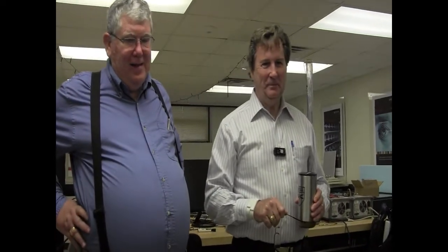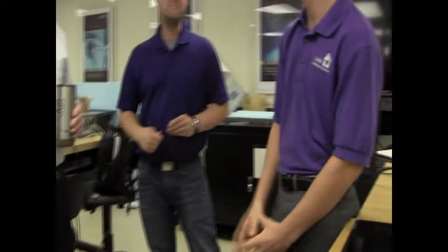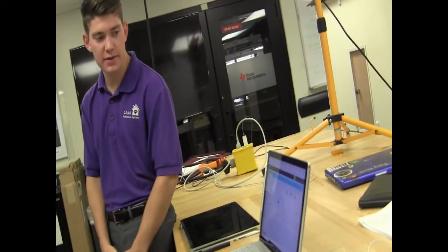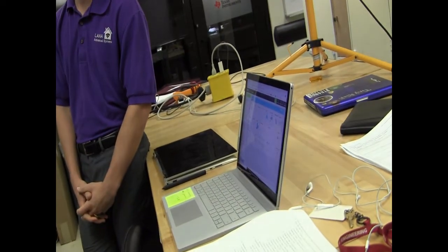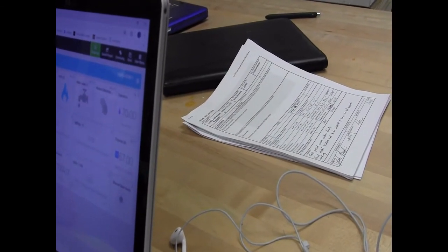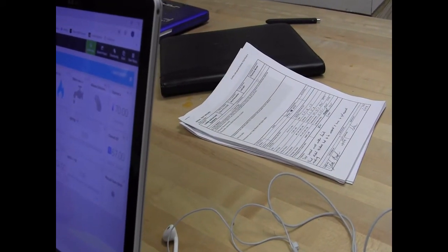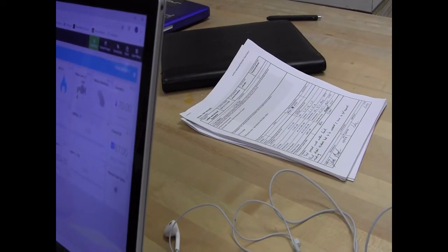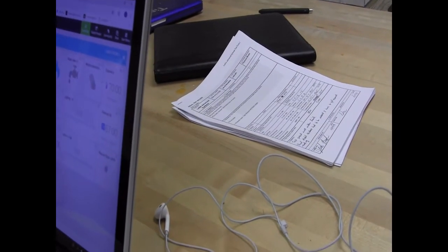So when you switch from one mode to another, there's a pause, normally 3 to 5 minutes. It's coming down. It's already dropped 7 degrees, it's at 70 degrees. You see up here. It sounds like it might have frozen, because the dump vent might not be fully open. And our other rooms have a different set point, so most of them have already been closed. That's mostly why it got closed.